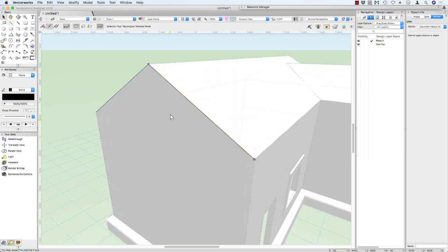And just notice I'm using this blue plane. I'm going to use my offset tool again, back to the offset original. So we're going to offset that line. We're going to use the Alt or Command key to offset that other one. I've got those two. I really want that line to project down there, and this line project down here. I need those to project beyond the building.